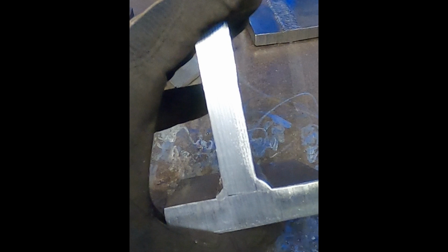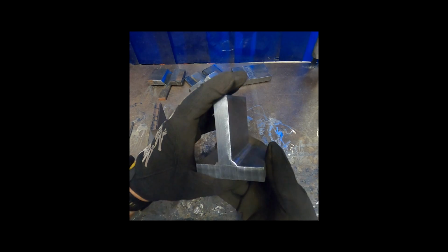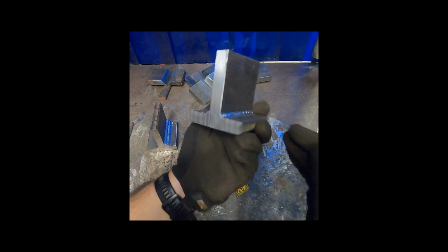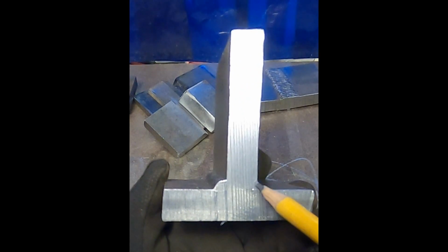There's a little bit more buildup than there is with the 6010. And I know you can see a little bit of a space or a gap in between the two plates. This wasn't because of a flaw in my welding. This was actually a flaw in my fit up. You can see that one weld has shorter legs than the other. You can start looking at things like the toes of the weld, the face of the weld.